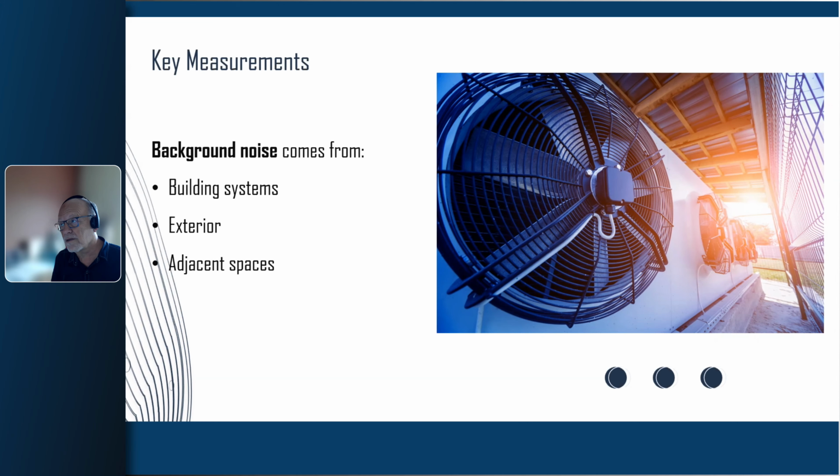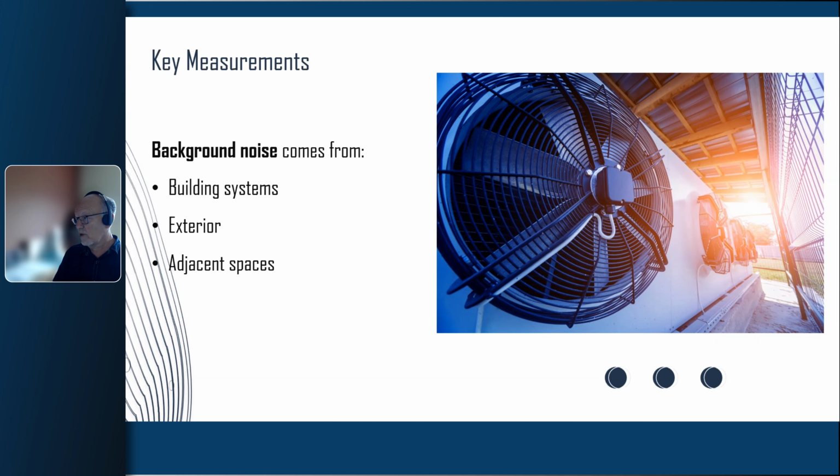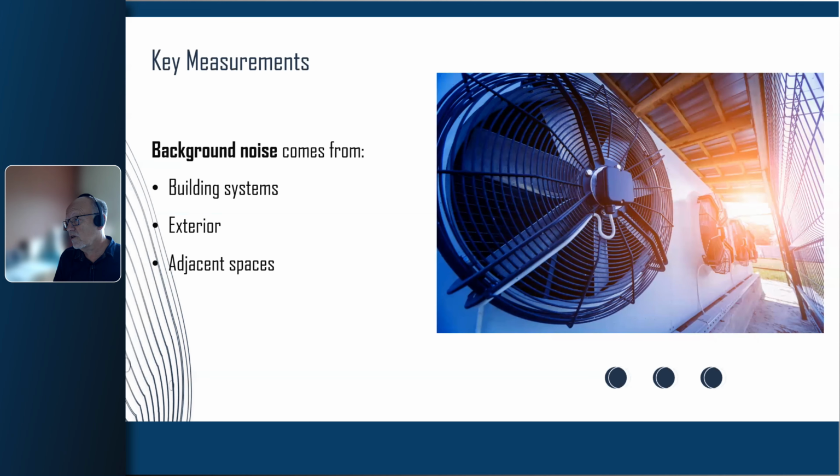We have a problem here. I don't know what the problem is. It could be the electrical boxes, it could be the floors, it could be the ceiling, it could be the door and frame, it could be all kinds of things. But we've got to get that NIC rating up to the high 40s, if not 50. So, I don't know, John, if that answers your question.